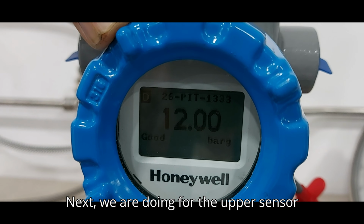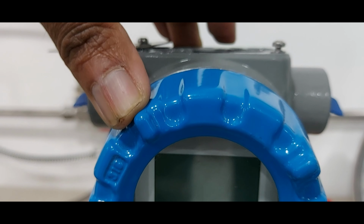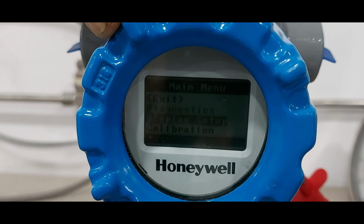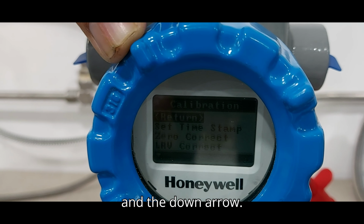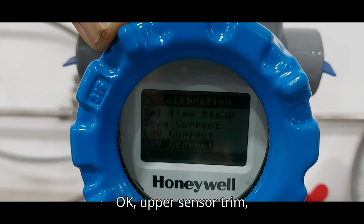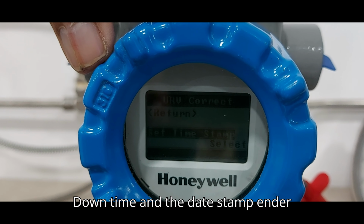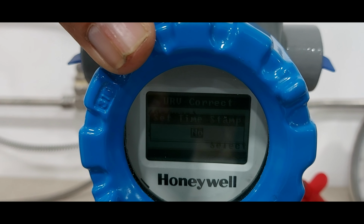Next we are doing the upper sensor trim. First press the enter button. The menu is showing on the display. Next select the down arrow and the calibration menu, select it, enter, and the down arrow. Upper sensor trim, select it and select the time and date stamp, enter, and press no, enter.